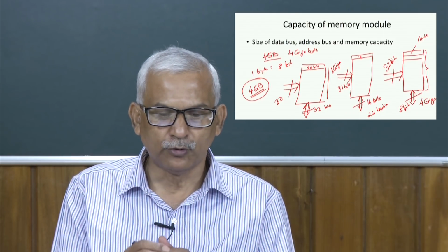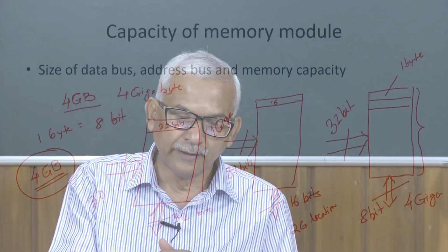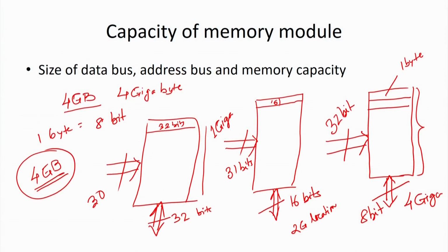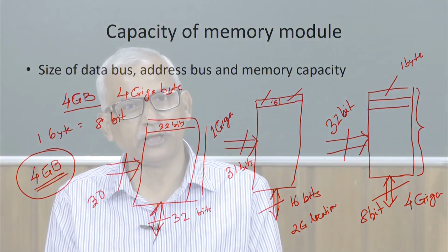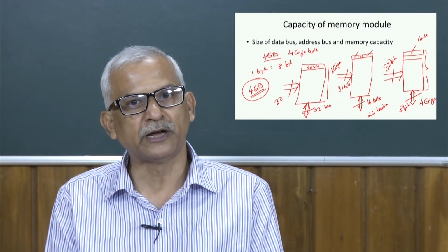Again we have some more concepts, called byte addressable. That means though I am having 2 bytes in one memory location, we can address byte wise also. I can take 8 bit and 8 bit. So, if I go into that, then the size of the address bus will be slightly different. You have to recalculate it. Again it will turn out to be 32 only.